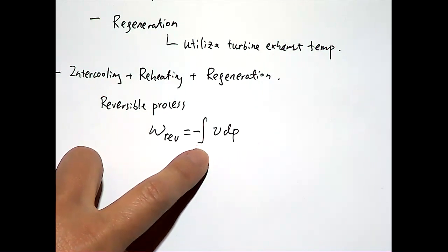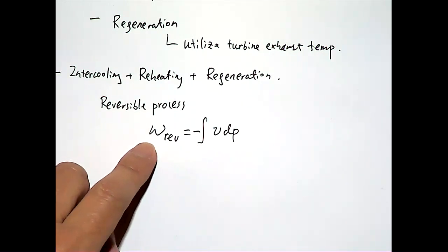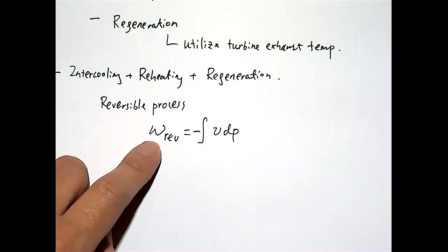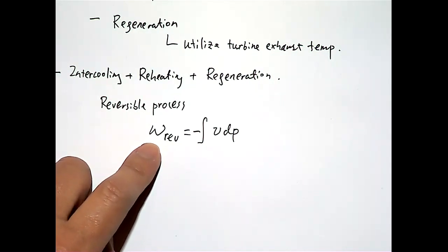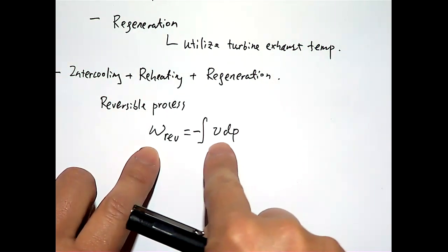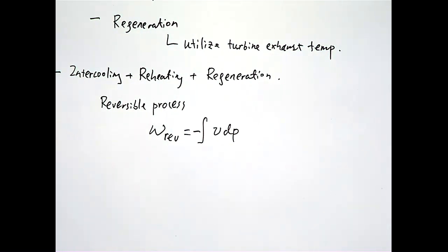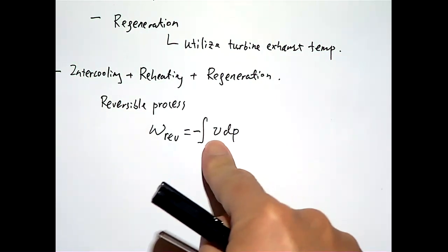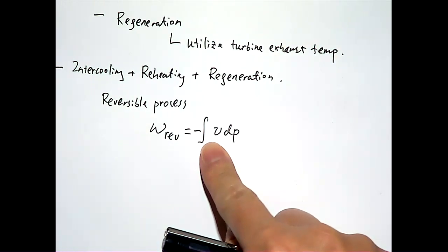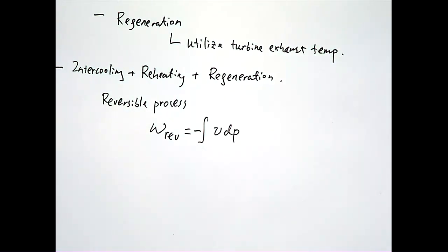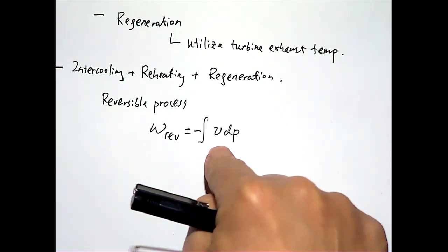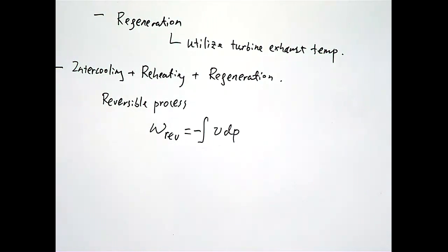But going through a compressor, if we want to minimize the work that is done externally to the gas, you want to keep the volume as small as possible, so that you can minimize the work done to the system, right? Let's say it's an ideal process, isentropic, which means the volume will go down during the compression process.